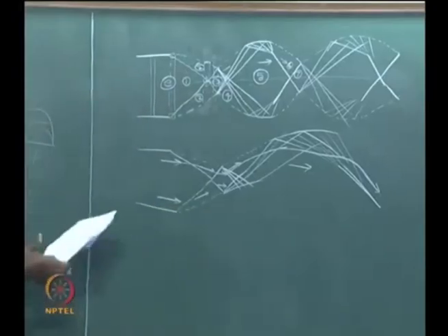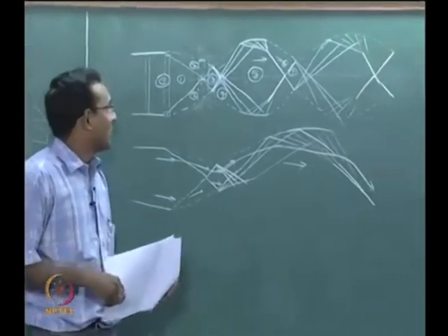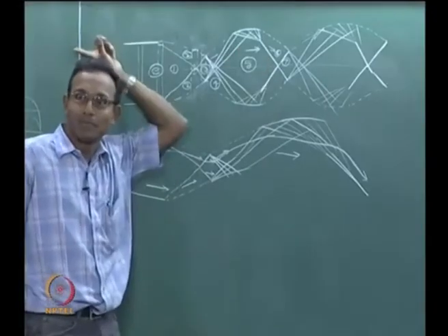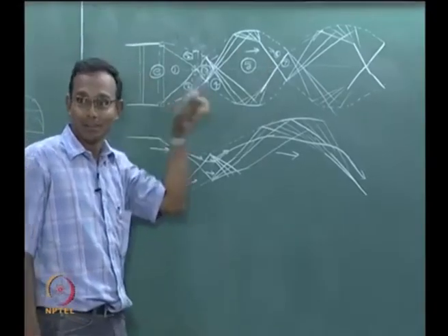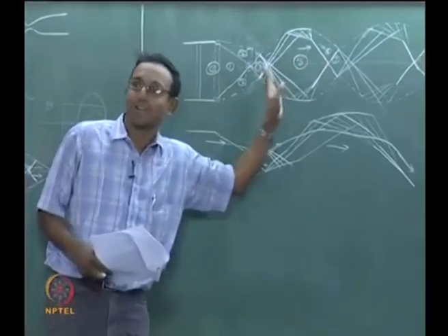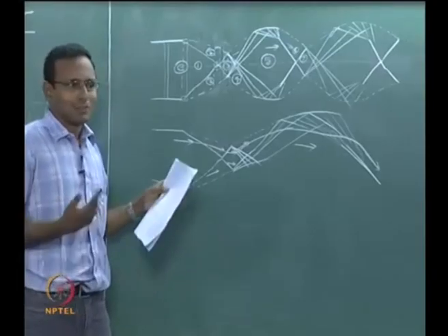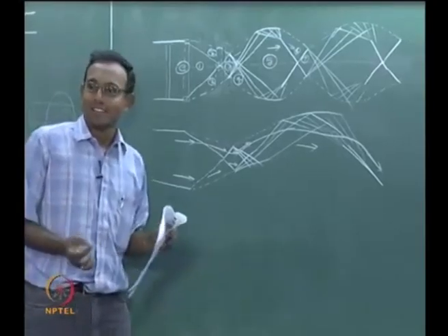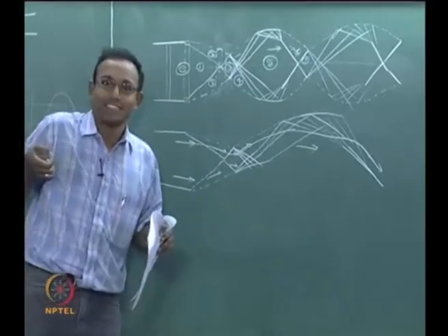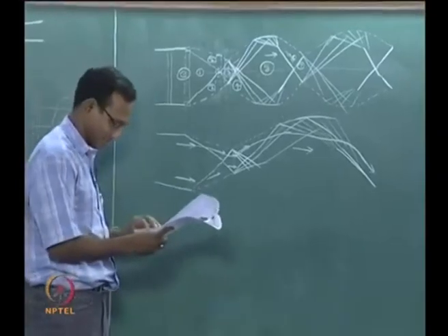Okay? There will be a time when I will ask you a question where I am going to put a pressure transducer somewhere here and I am going to change my P naught in my nozzle. That is a beautiful problem to solve. I am just leading you in that direction right now. If you solve that problem, you can solve a problem of a cycle tube being punctured by a pin and put a pressure transducer outside. What will you see? More practical problem to solve. So many things can be done.